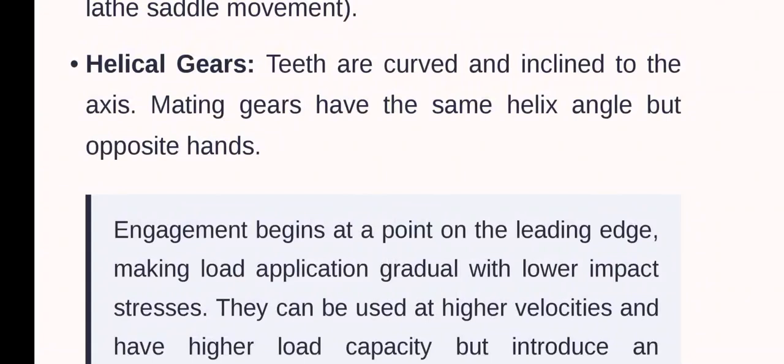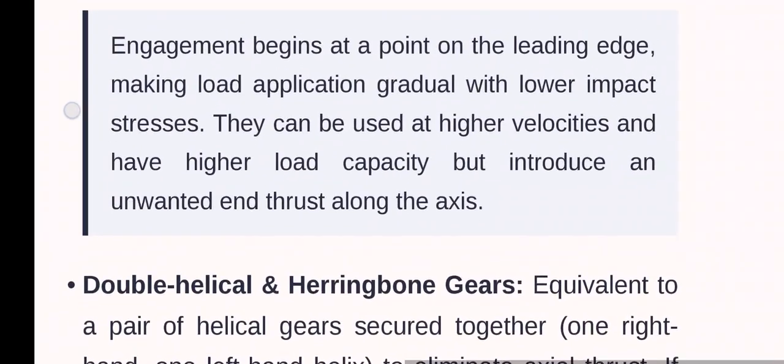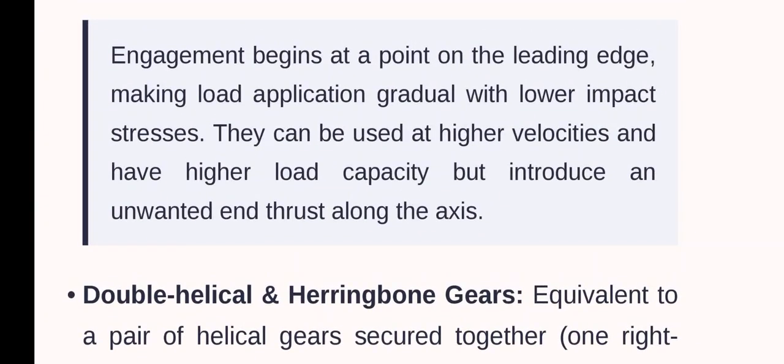Helical gears. Teeth are curved and inclined to the axis. Mating gears have the same helix angle but opposite hands. Engagement begins at a point on the leading edge, making load application gradual with lower impact stress. They can be used at high velocity and have higher load capacity but introduce an unwanted end thrust along the axis.